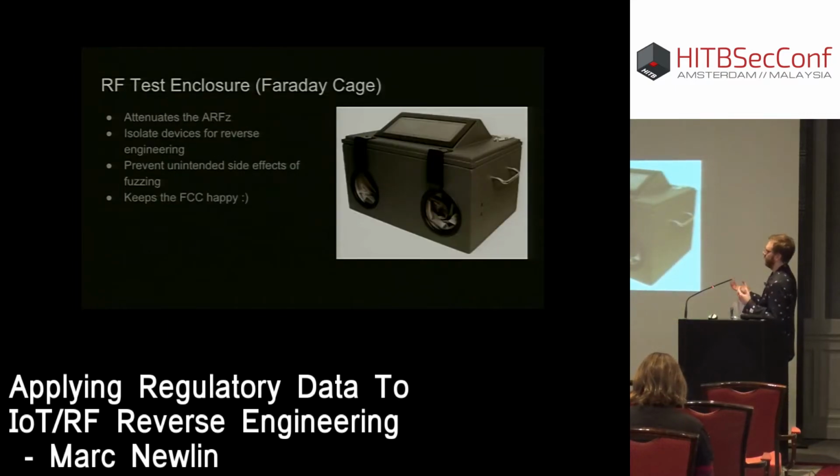This is an example RF test enclosure. This is what we use at work. These things are really, really fantastic because you can put your devices in there, SMA cable out to your software-defined radio, USB out to your computer. And so you can interact with your SDR and your device the same way as you would out in the open, but you're protected from everything in the environment. For determining exactly what a device is doing, this is very valuable because you can know for certain that you're not looking at traffic coming from something else in the world.